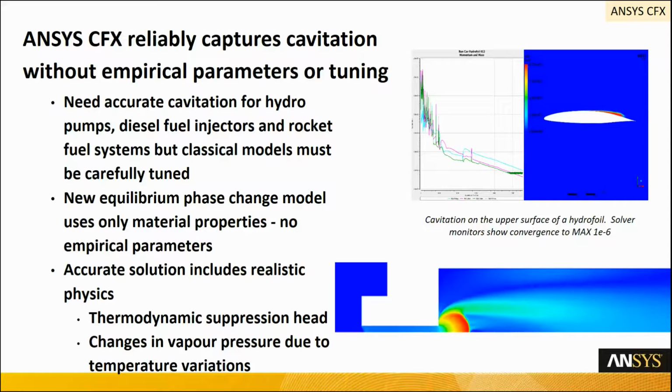This means that you no longer have recourse to models such as Rayleigh-Plesset or the need to tune rate constants, etc., because the occurrence or not of cavitation depends solely on the thermodynamic state, and that means that it automatically takes into account effects arising from local changes in pressure or temperature.